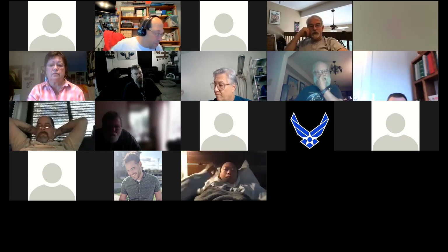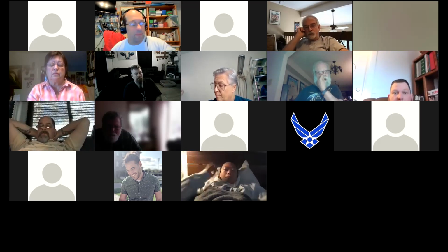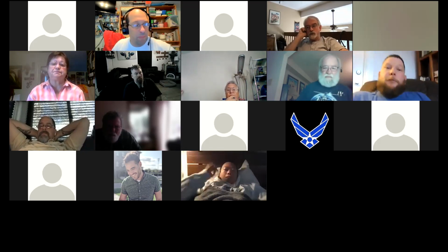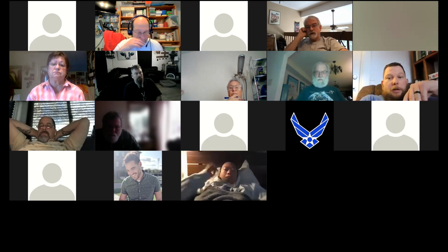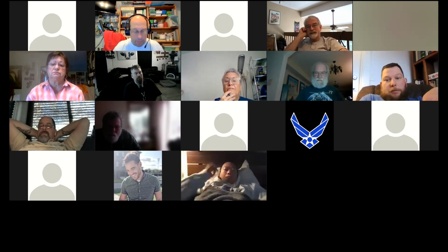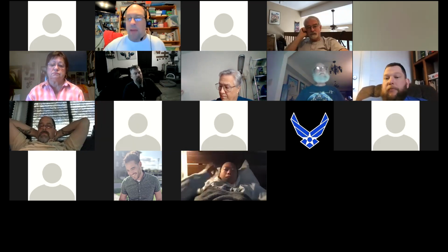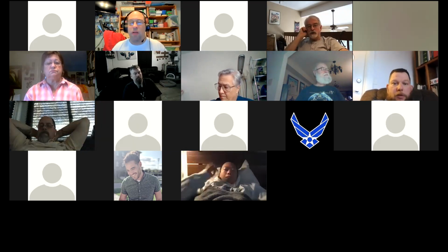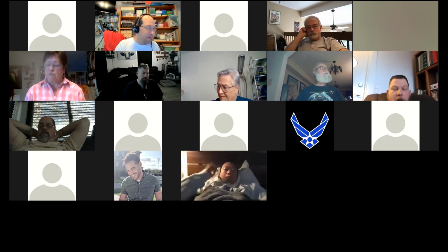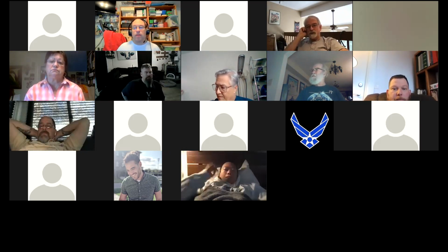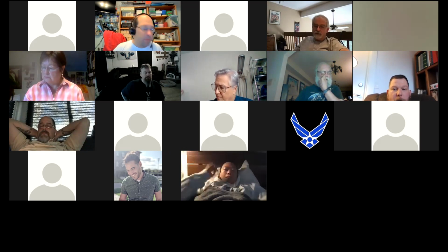Got a question for you. Real world, using that tool right there, what is a real world SWR? What is commonly seen and accepted? In other words, what are you aiming for? Well, I know what you're aiming for, but in the real world, ivory towers are what you want, but sometimes you get there. If I get down to 1.5 to 1, I'm happy. All right, that's what I wanted to know.